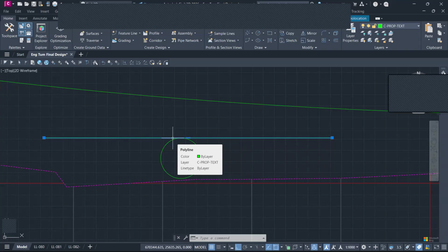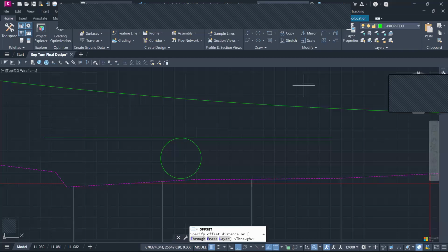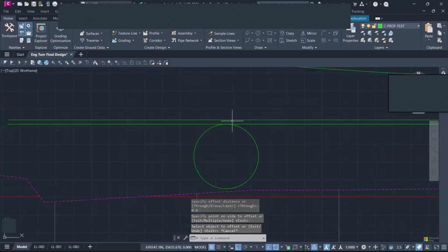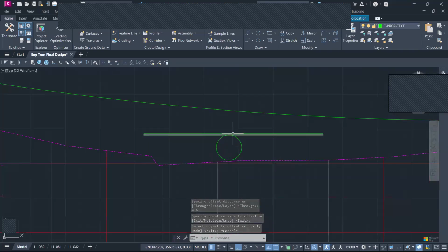So you do the 150. Then on top of that, you account for the 0.6 meters before you start laying your pavement, to ensure that the vehicle does not damage the culvert. So let me do 0.6. So you will notice that is 0.6 at that point. This is, of course, based on the scale that I've adopted.